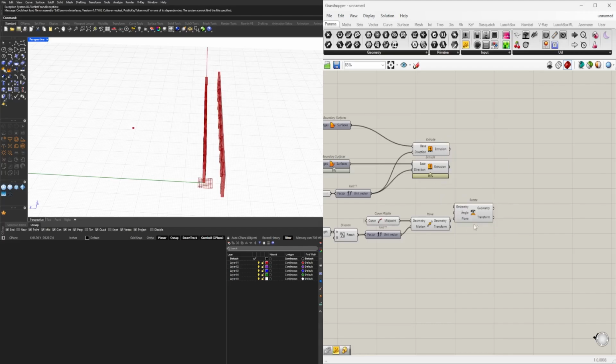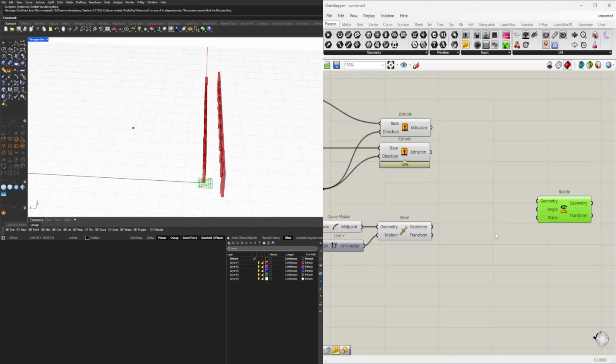Using rotate, we can also use polar array, but I like to use rotate, and this is how I like to use it. If I'm rotating something symmetrically, it's usually using 360 degrees. And so we do 360 divided by 4 because we're rotating it 4 times. So 360, you can just do division. And then here I'll show you, I'll use quotation marks 4 to create a panel that has that number. And so 360 divided by 4 equals 90.